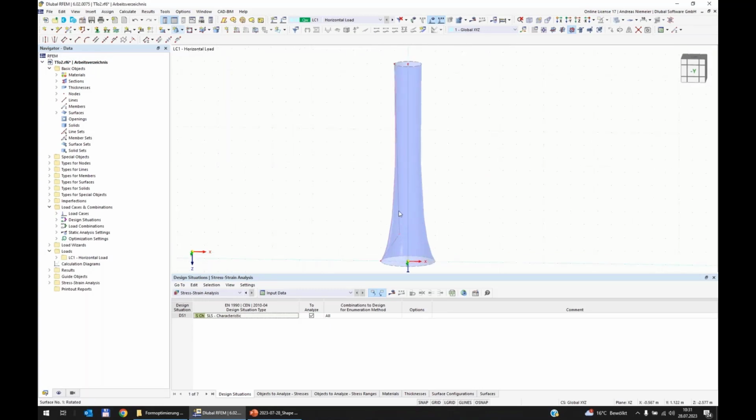So we can also consider in our parameters a constriction, maybe an x-level of the constriction with a direction of the constriction. And now we give the computer control of this constriction point, because I can always change the point, run steel design, check weight and utilization, and see if it's good or not. So we have a lot of situations here. Now this is the point where we can try to see if this could be solved numerically. And for this, I prepared something.